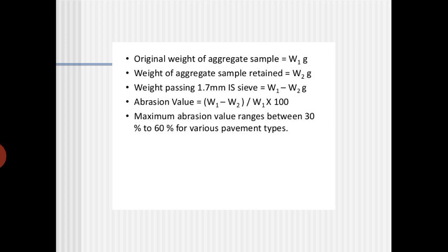Then the normal maximum abrasion value between 32 and 60% for the various pavements can be used, but not more than 60%. If the abrasion value is more than 60%, then this aggregate is rejected.